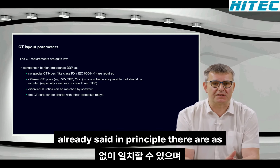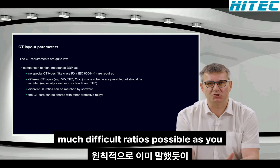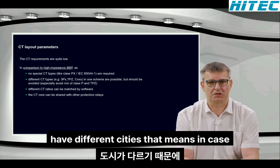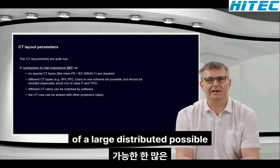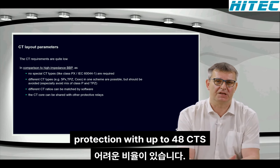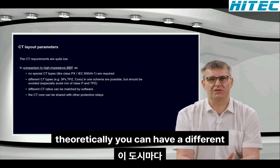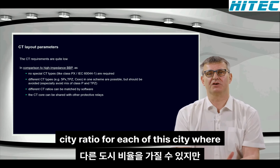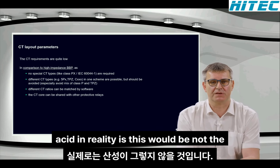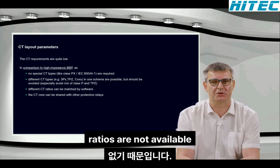As already said, in principle there are as many different ratios possible as you have different CTs. That means in case of a large distributed busbar protection with up to 48 CTs, theoretically you can have a different CT ratio for each of these CTs, whereas in reality this would not be the case, I guess, because so many different ratios are not available.